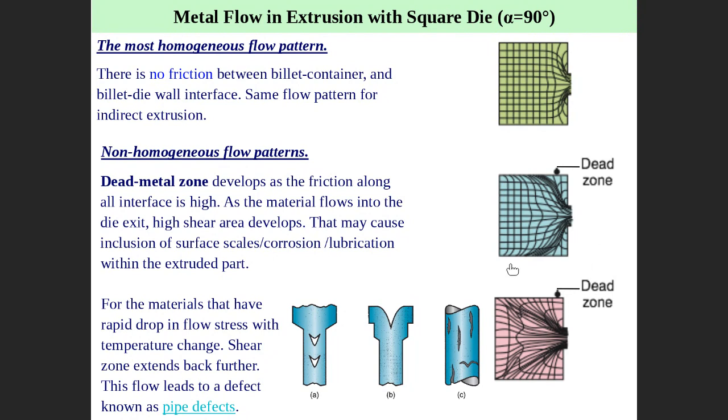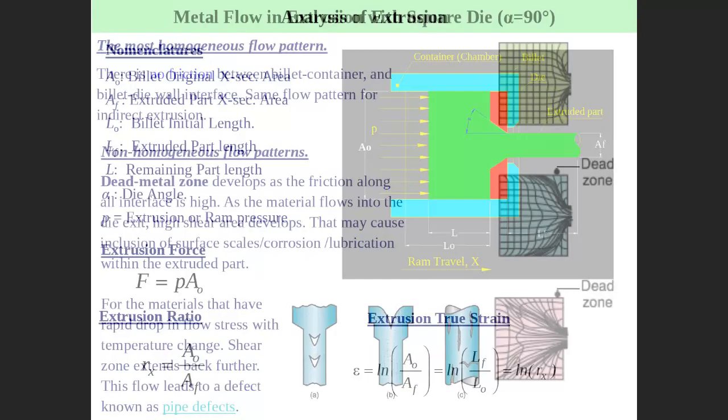For sure, we need to lubricate here. In general, we need to lubricate whether you talk about cold working, hot working or warm working. In all cases, you need to lubricate to reduce the effect of the dead zone, because friction significantly affects the process. Many defects are also produced if you do not lubricate properly. I will discuss the defects at the end of this process.